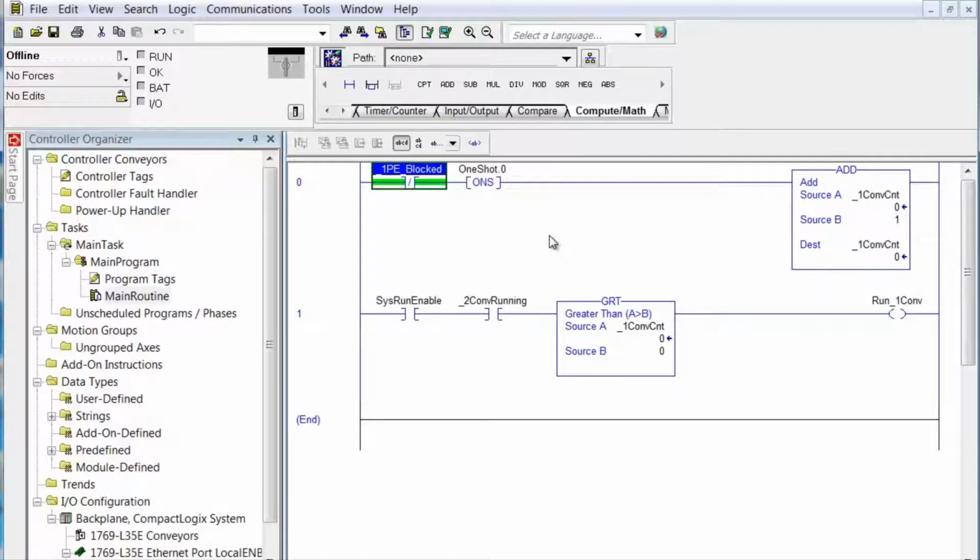Now, in the manual, when you got to this point, it had a little description of this rung, and on this instruction it said, on the trailing edge of a carton leaving 2 PE, one shot the add instruction. This increments the count each event of a carton clearing 2 PE onto 2 conveyor. You probably have seen the error we mentioned, actually clearing 2 PE onto 1 conveyor. So it's not an error as far as code writing goes, it's less than optimum logic.